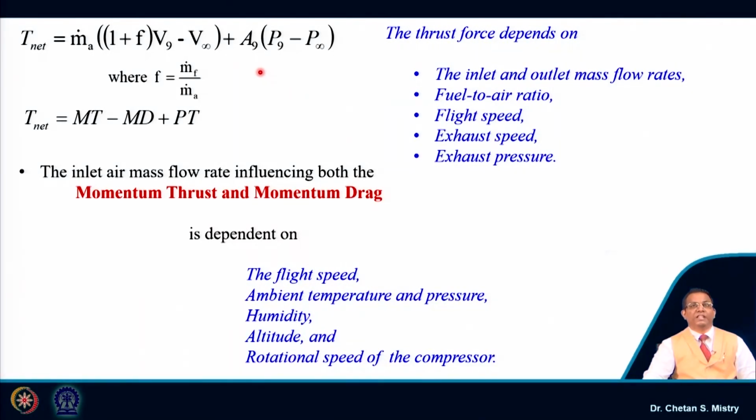If you consider this area, at this moment the area of the nozzle is constant. The scenario is changed now. We will have a variable area nozzle. A number of engines which are available now have a variable area nozzle. Mainly for fighter aircraft, this area A9 that we are discussing will be varied as per the requirement. So, in the next week when we discuss the performance of different components, we will be touching this part.